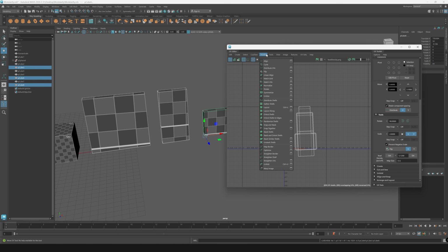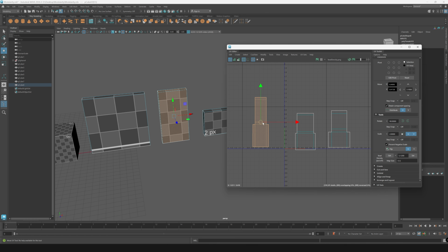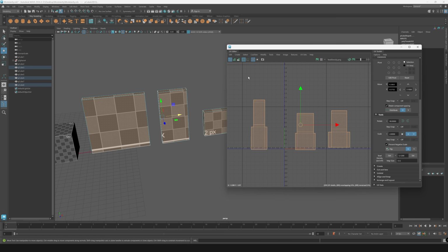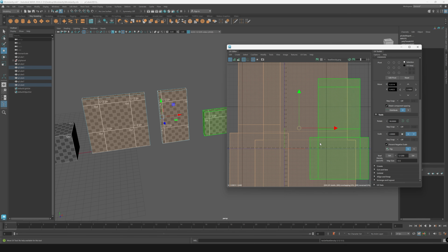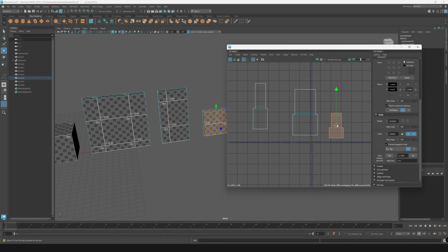Then from our modify, we'll do an orient shell, which will snap the rotations to the closest 90 degrees. And then now let's just grab the UV shell so we can separate all these guys. Okay, so it looks like we have all of them here. Now let's quickly set the texel density. Now they're all at the same consistent texel density, but let me just quickly fix some things on here, because what's happening is each one of these guys flips kind of upside down, more or less.